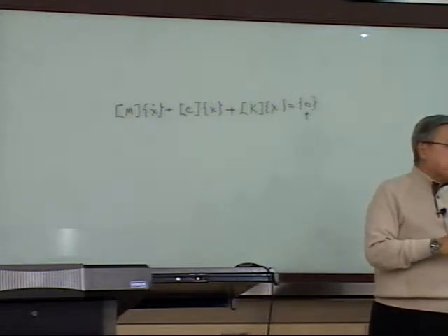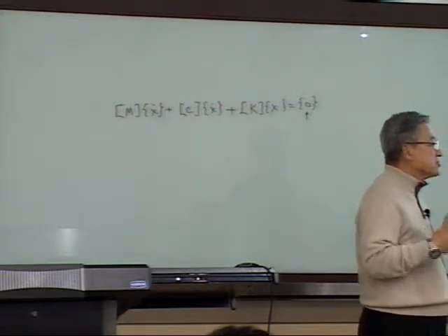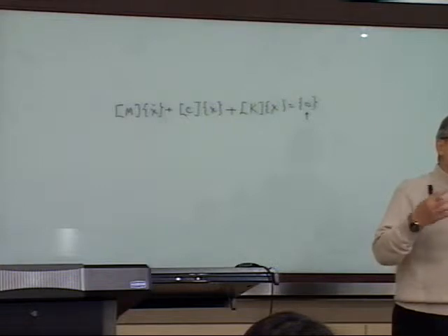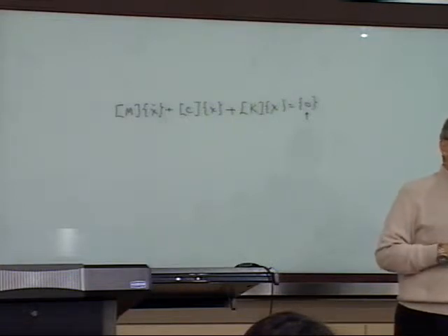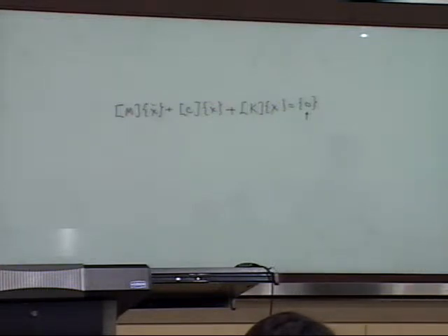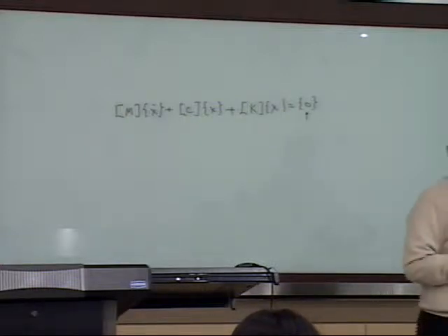Damping introduces energy dissipation in the system. And the damping effect in structural dynamics is usually very small. I mentioned in terms of zeta, the damping ratio, the zeta value is, for design purposes, about 2%. Okay? That's not really the material damping. It comes from the built-up structure, like joints in the system.